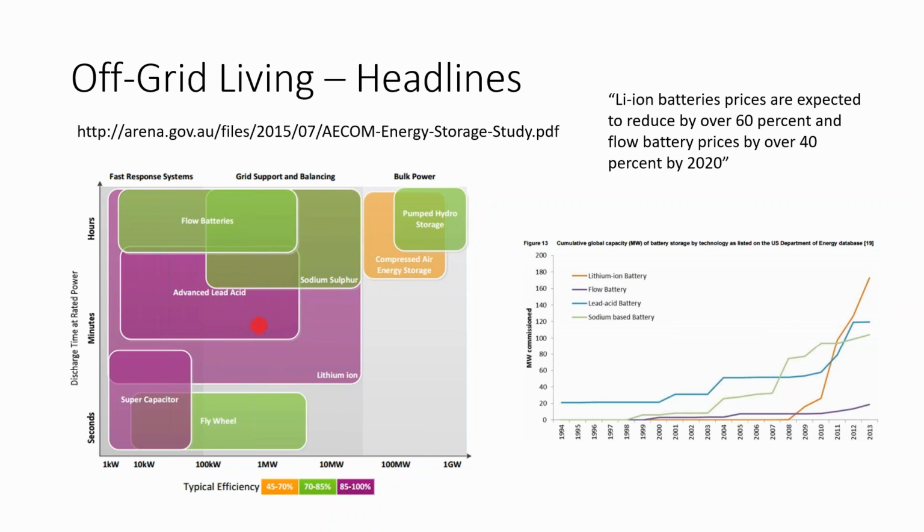What you're really losing compared to lead acid versus lithium ion, and lithium ion will have that same problem when they're discharging, it's just it'll be to a more efficient extent. And so you look at the round trip efficiency of how much energy went into the battery and how much energy came out of the battery, and lithium ion is going to be the more efficient system, which is very interesting when you think about it, because say out in California, they're doing lithium ion all over the place.